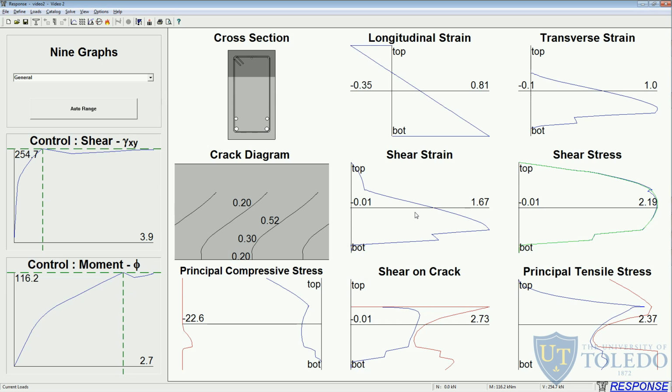Here on the left side, we can see both the moment curvature graph and the shear force versus shear strain chart. In our case, since our SAP2000 model from our previous video had a shear critical behavior where the shear hinges in SAP2000 basically control the entire behavior of our beam, we will only focus on changing the shear hinging by making it follow this curve right here in Response 2000.